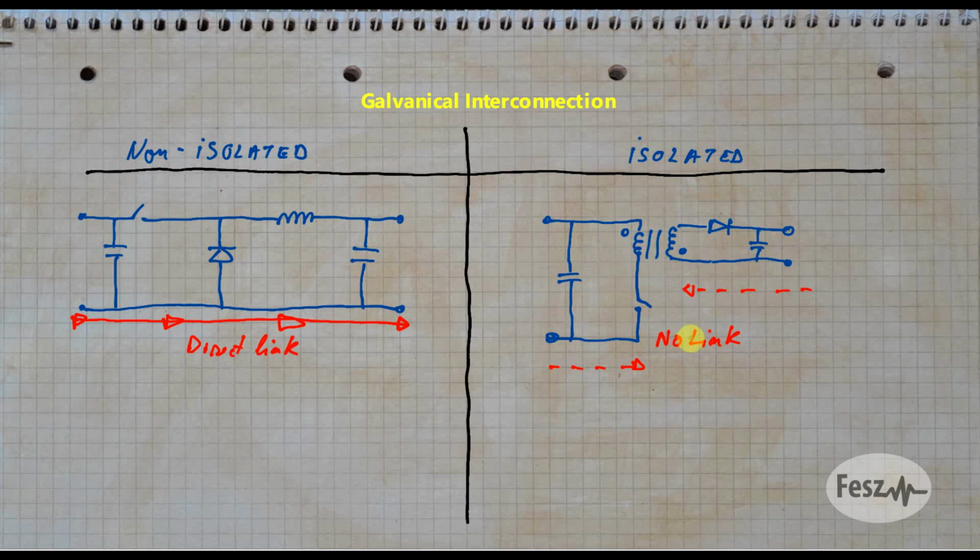Now, it's important to observe that since a transformer and complete separation is used, you can make the output of either larger, smaller, or even inverted value compared to the input. With isolating transformers, there is no dedicated topology based on the input to output voltage relationship anymore, since the main thing that decides the voltage ratio will be the turns ratio and the exact ground connection on the secondary side.